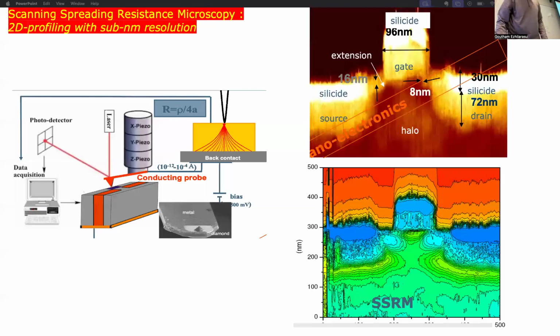So this is just something I added in. There was a question that Rehan asked as to how you physically measure. When you do the lightly doped drain region, how do you know that's the profile you get in practice? There is actually a way to physically see what the source drain regions look like, a technique called scanning spreading resistance microscopy. If you know what an AFM is, an atomic force microscope, this does electrical measurements as it scans the surface. It measures the resistivity at the surface as it's scanning.